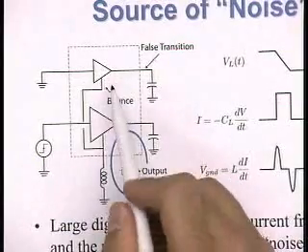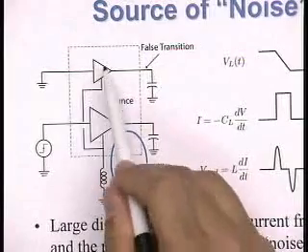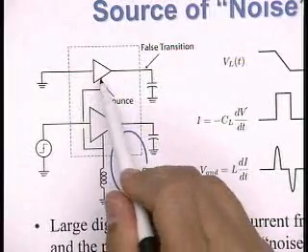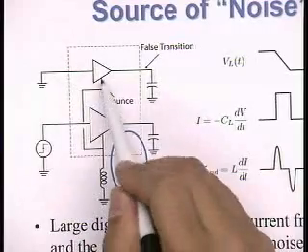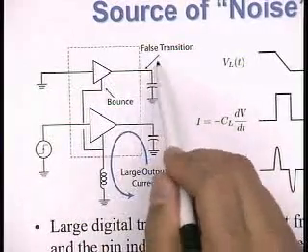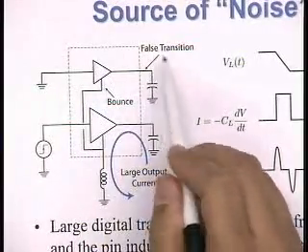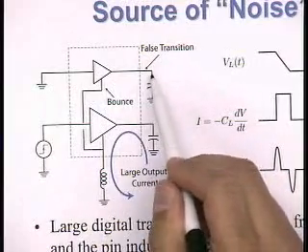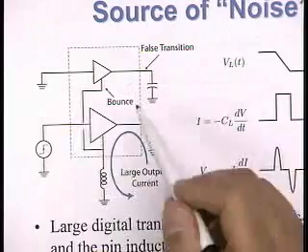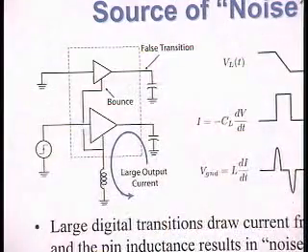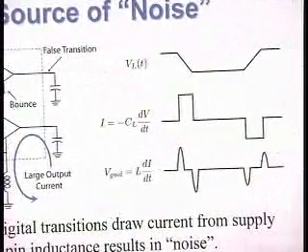And because I've got another gate here connected to this ground, let's say this gate is not supposed to transition during this cycle, but because of this voltage bounce, we may see a glitch waveform over here, and if we're so unlucky, that glitch could be captured by a latch, and so we have an error in our system due to this voltage bounce.